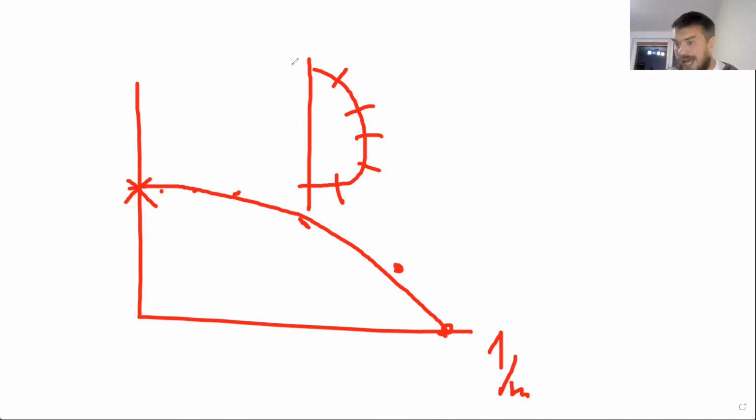But doing the actual mesh convergence, the scientific study, would take an insane amount of computing power. Practically speaking, this is what you should do. You can, of course, do the convergence check on a linear model and then use the mesh that converged in the linear analysis in the nonlinear analysis, although this approach is problematic, at least because you have stress concentration.